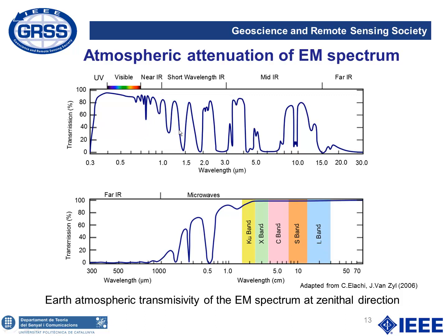And in the intermediate region, which is infrared, which is really a very wide region with many differences of scale, wavelengths and frequencies, you can see there are a lot of bands where we have either a window or an absorption region. So we have to be very careful working in the infrared to pick the correct window. Otherwise we will get no information of the surface, although we might get information on the gases of the atmosphere where this interaction is taking place.